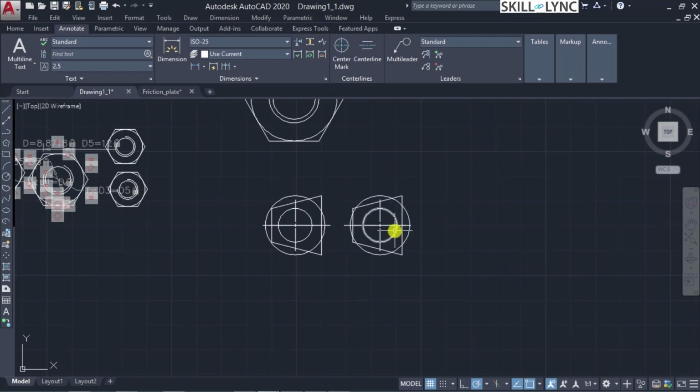So the idea here is we are going to use either of these images to switch between the first and third angle projections using the visibility command. So that's what we've done. We have duplicated these two images and then overlapped them, and now we're going to create a separate block so that it can be edited and modified in the block editor.